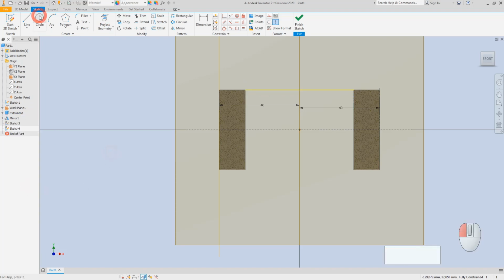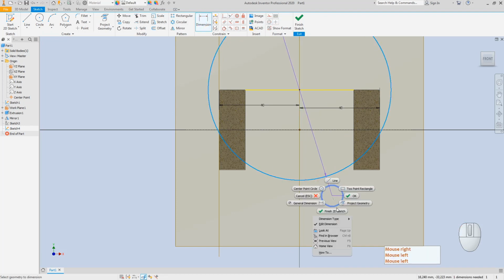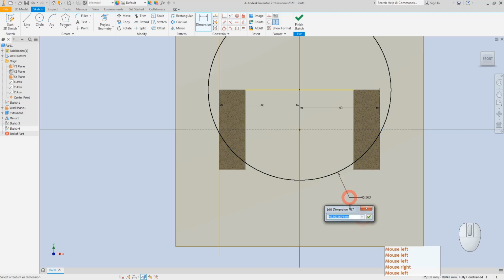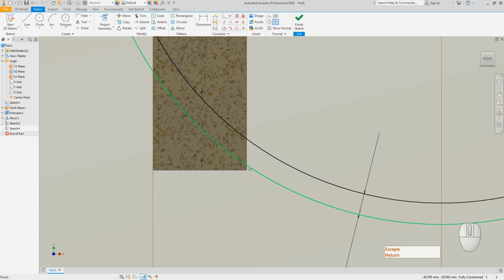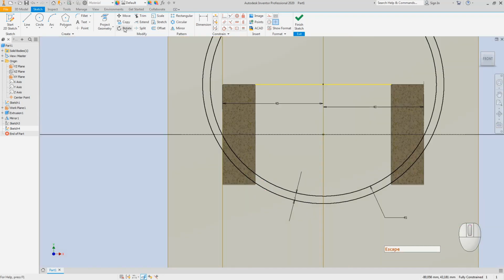make this sketch invisible, and create 1 circle here. I'm going to use only this arc shape by having the dimension 45 like this. And our shape will just start after this one. I will just get the offset, and this offset, the dimension here, it is 3 millimeters. As you see, we have that offset at this point.